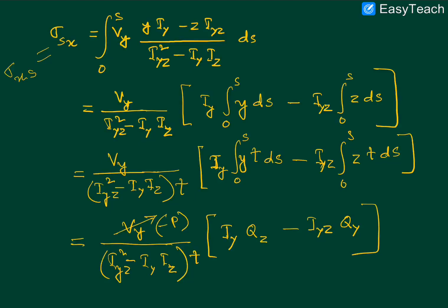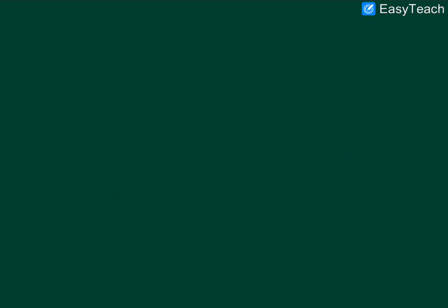and to equate that to the externally applied torsional moment. So you note that if we take the torsional moment of this sigma xs contribution about any axis, this P is going to be present there, and if I balance this against the torsional moment which is actually contributed by the given applied load, which is P itself, so from that balance this P is going to cancel out with that P. So the idea is like this.